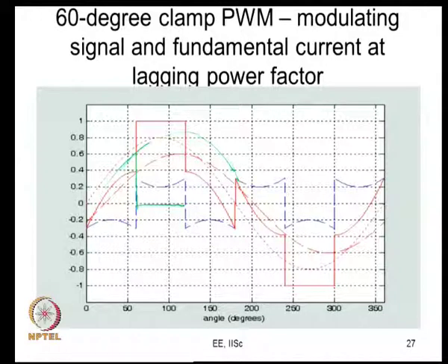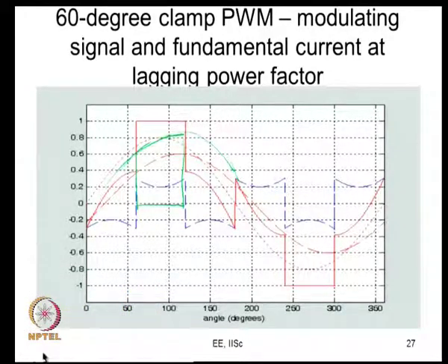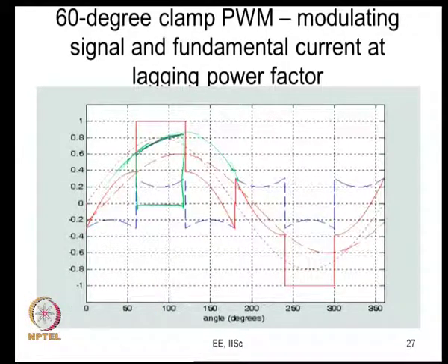During this region your loss is reduced. Let me draw this with a different color, so let us say here. What should have been so much is now reduced here. So, you get a certain amount of savings in the switching energy. During this time you do not save. So, for the same amplitude of current, at a different power factor, the switching loss is now lower.